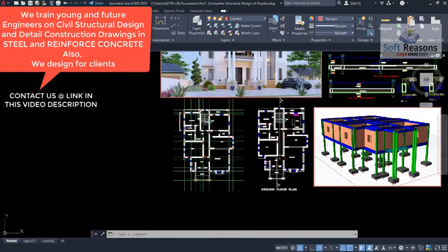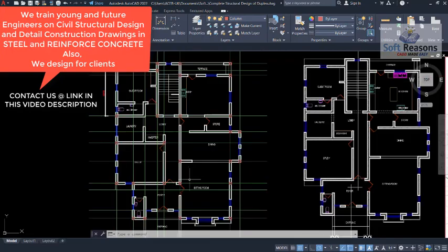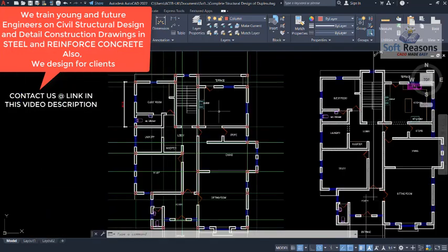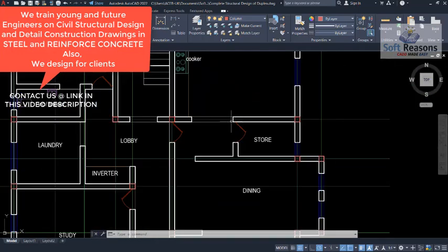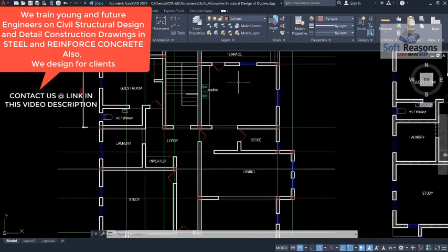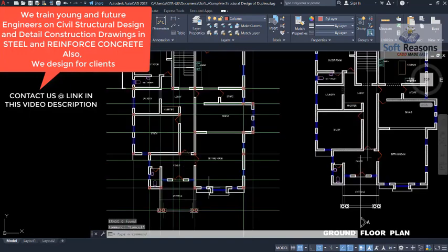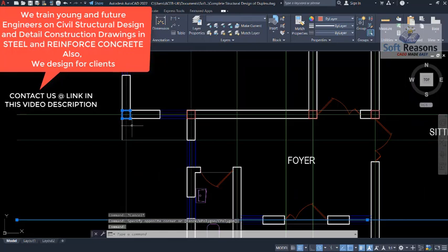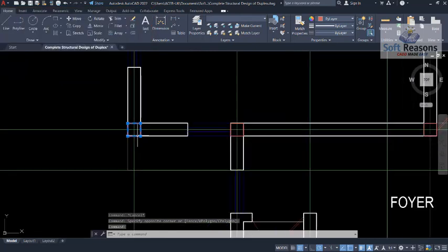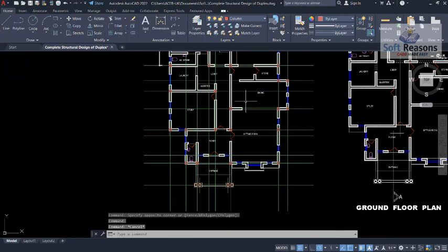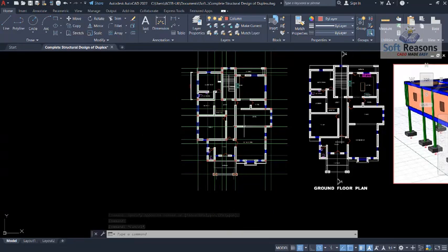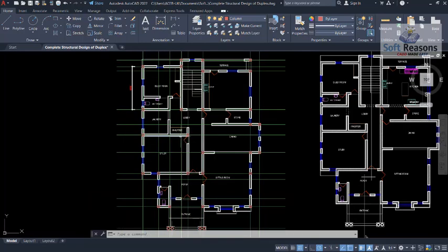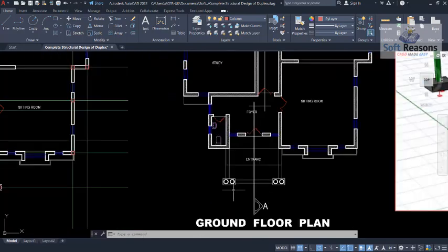So by the time I get these plans to ProtaStructure, you wouldn't see all of those kitchen units, because ProtaStructure cannot detect all of that. The only things ProtaStructure can detect here are the grid lines and the reinforced concrete column layers. So these are the 2 layers that are very necessary. You create them in AutoCAD, and then plan them on the building plan successfully.